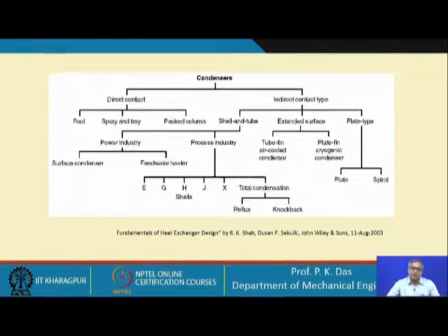The feed water we get from the condenser is raised to a high pressure with the help of a pump, but the saturation temperature corresponding to that high pressure is really large, and that temperature we do not get at the outlet of the pump. So, the liquid water has to be heated to the saturation temperature.